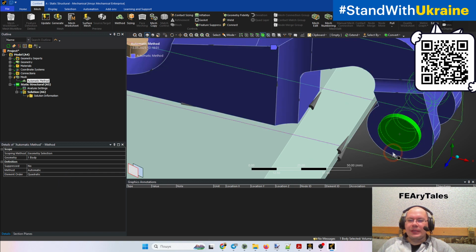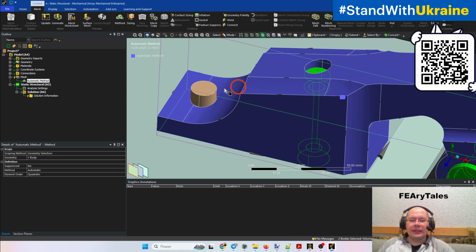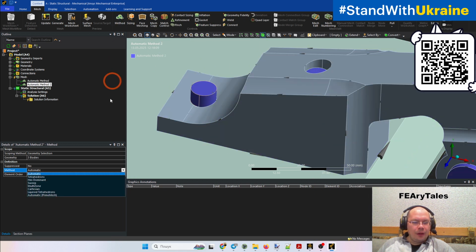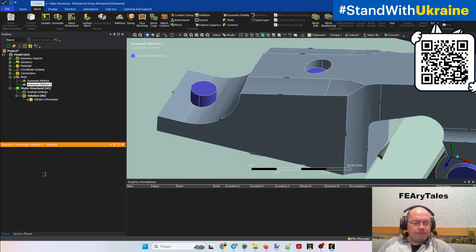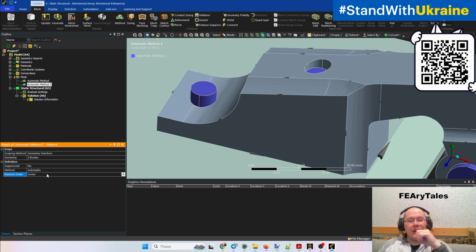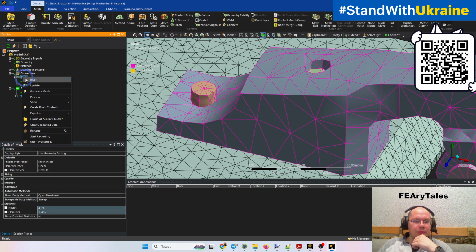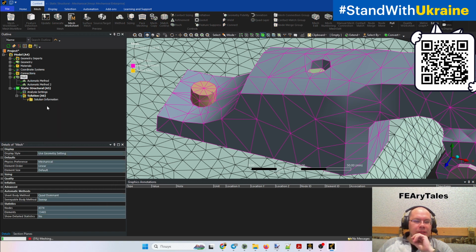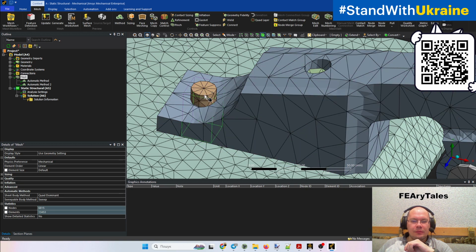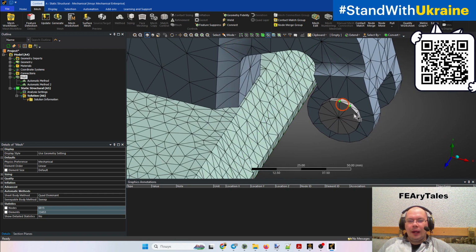And for example, for this body, let's change the option to linear, no matter what we chose previously. So when we create those elements now, those objects will have the linear mesh, like it looks in the global preferences, and like it looks in our additional preferences.